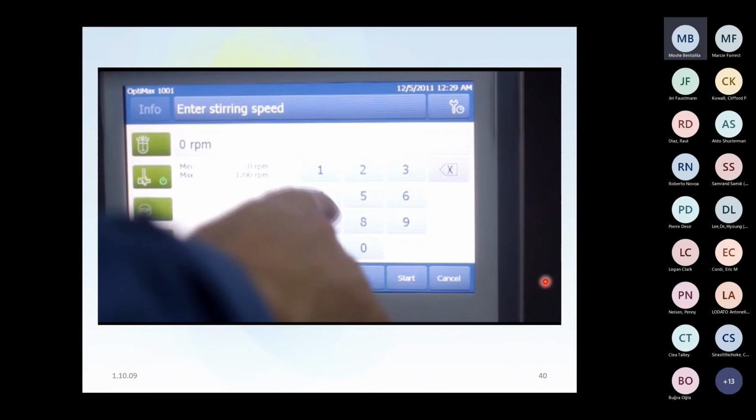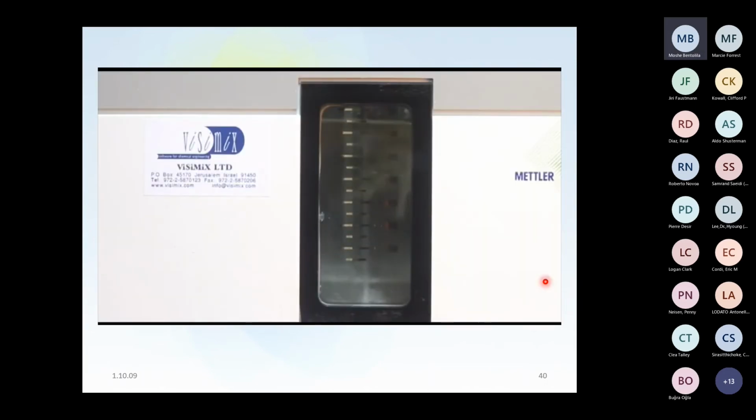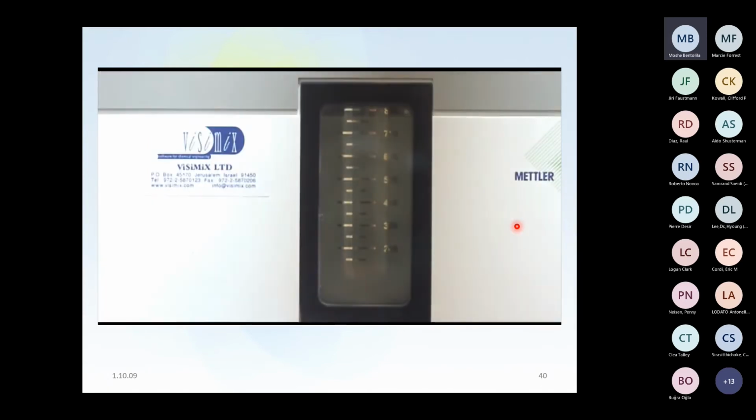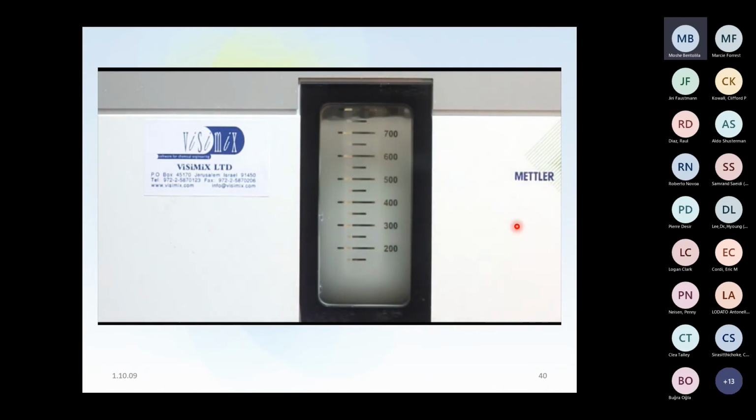Now, if we go to 400 RPM, but now after we generate our representative time, it's about 5 minutes, and I apply high shear rate with the rotor stator that I add here, what will happen now? We apply the rotor stator, high shear rate, 2 orders of magnitude more in the shear rate. What you get, you see, wow, now in a few seconds, you see that we have very, very small drop size. And when we stop the RPM, what will happen here is that we will not have phase separation. Now, is it good or no good? What is good means in here?